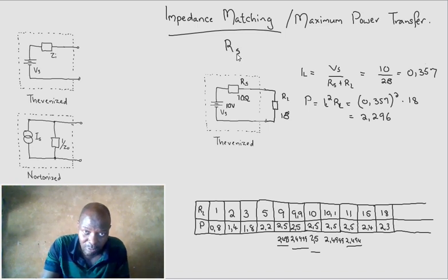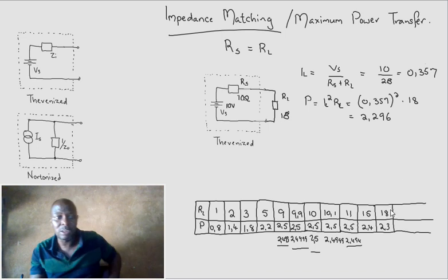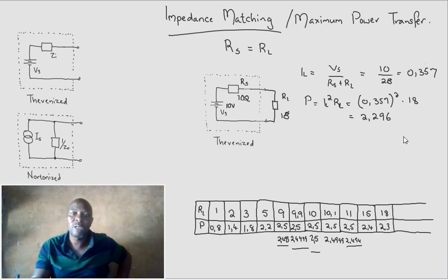That must be the same as the load impedance. That way you've got maximum power transfer. You're going to have your maximum power. As you can see, our power peaked at exactly 2.5. Below it was slightly lower than 2.5. Rounding off makes it look like it was 2.5.